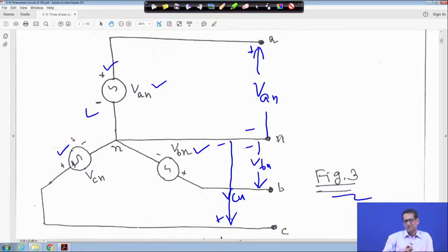So basically you have a magnet that is rotating, and it is surrounded by a static part called the stator, where windings are placed 120 degrees apart, right? As the magnet rotates, voltage will be induced in all these three different coils, which are physically 120 degrees apart, right? If we take the voltage induced in VAN as a reference, then VBN lags VAN by 120 degrees and VCN lags VBN by 120 degrees, otherwise VCN lags VAN by 240 degrees, right?